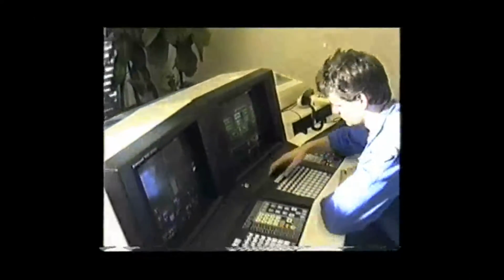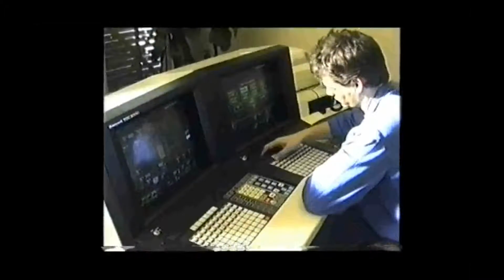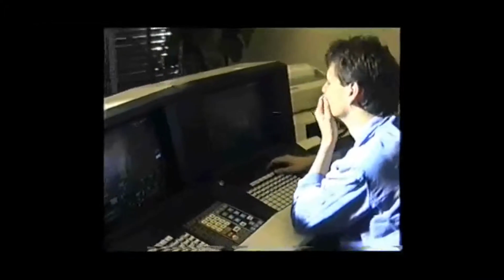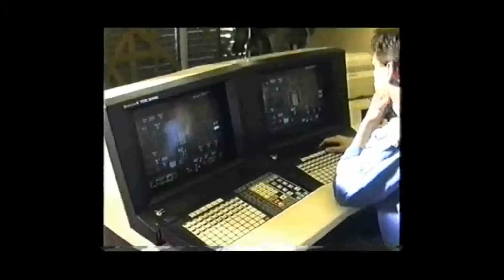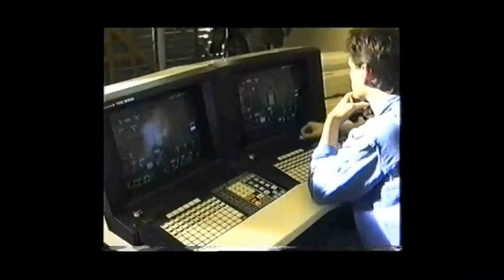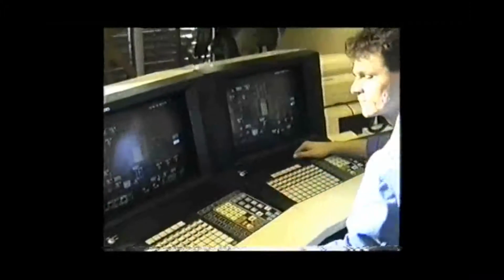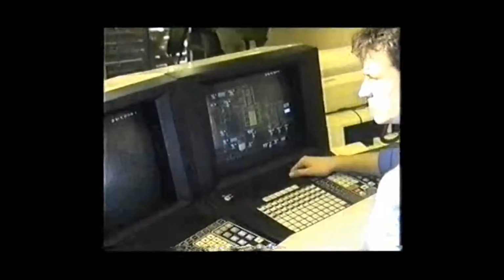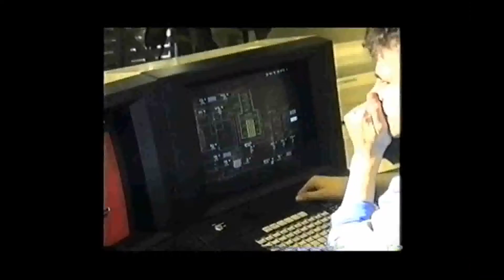All data are recorded electronically as trends. The operator understands the function of every controller and indicator directly from piping and instrumentation diagram. Now, one controller, a software and hardware situated behind the control room, replaces single loop controllers.